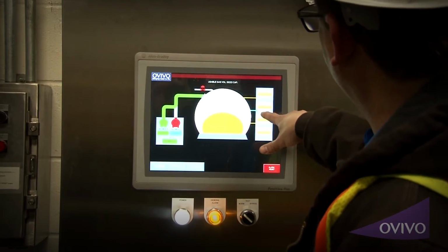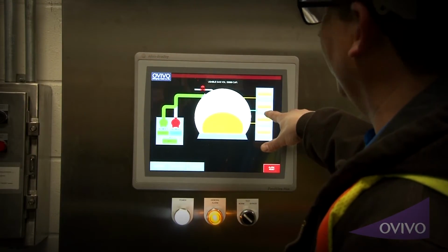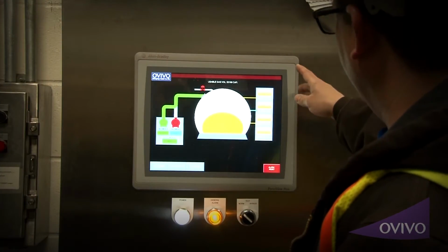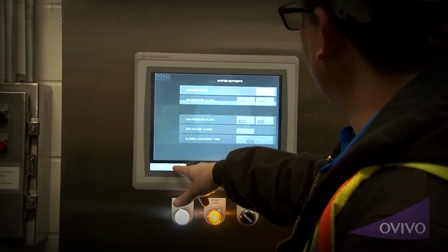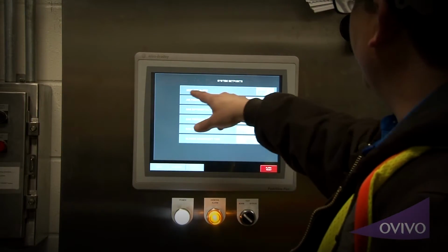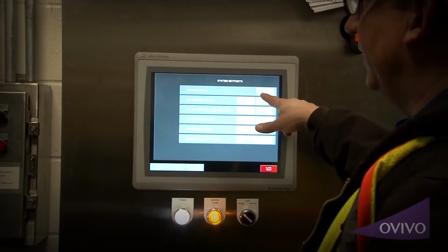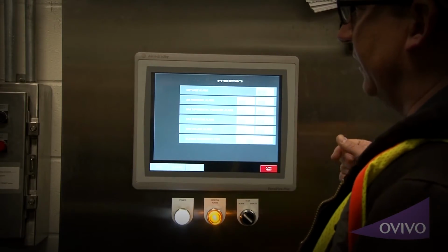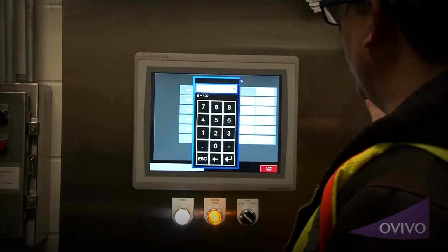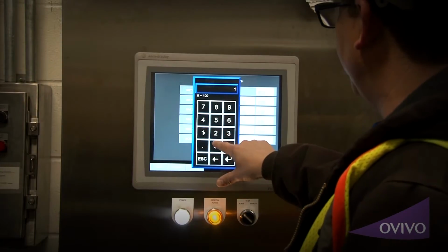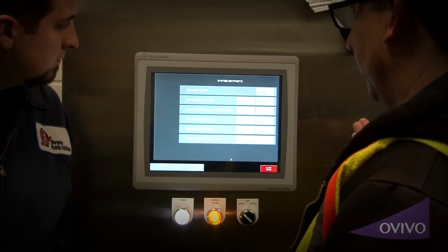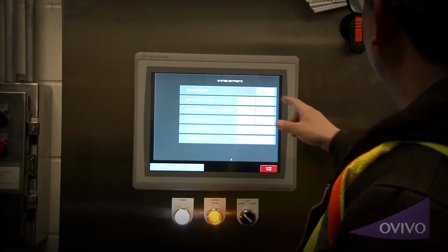These are how it's running, and you can see it actually fluctuating between 13.2 and it was 12.9 before. That's just going to happen. That's standard. And if you ever wanted to, you can go into your set points, because your set points will go off and it'll start alarming you. The methane alarm goes off at 35%. If for some reason you say, hey, listen, I want to know well before 35%, it's just an alarm. You can go in and take it to whatever you want it to. I want to know at 10%. And that's 10% of LEL, so that's 0.44% of methane.